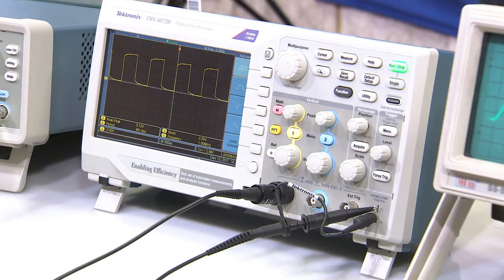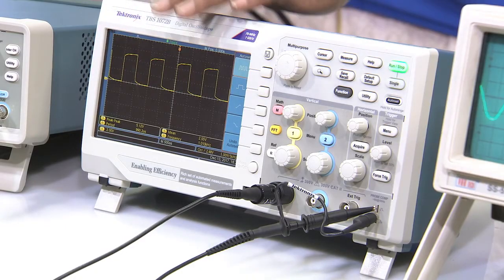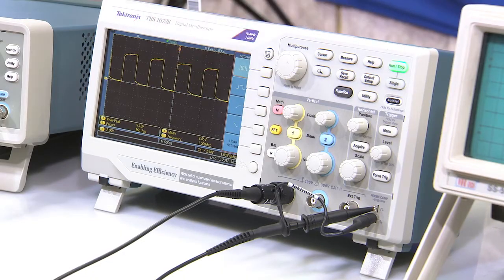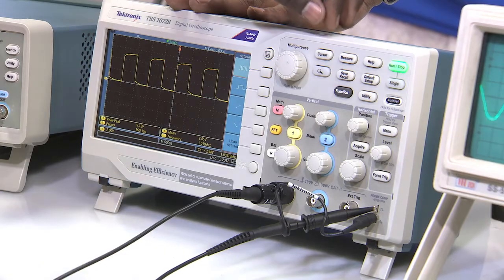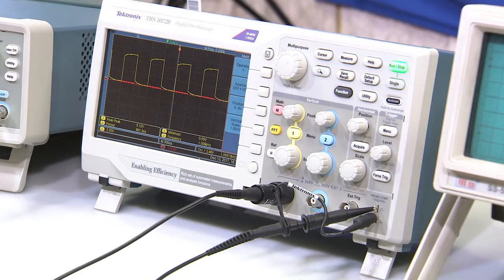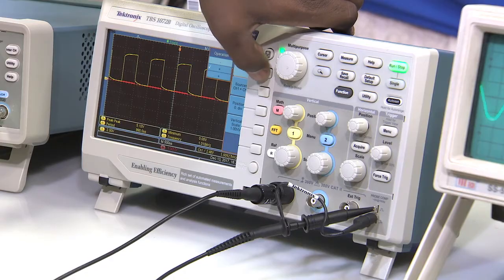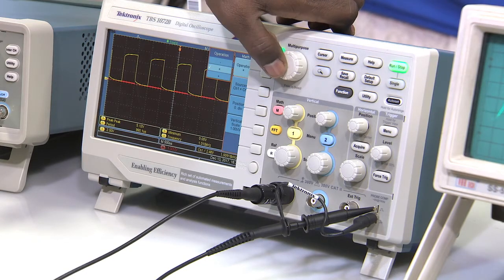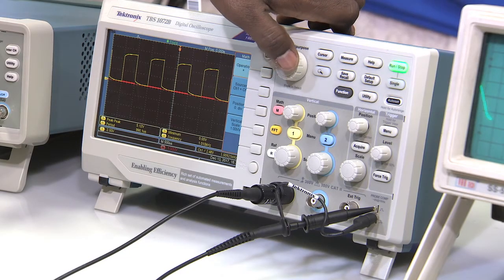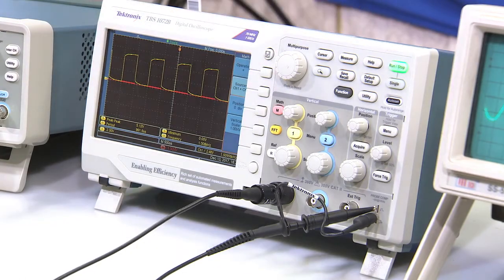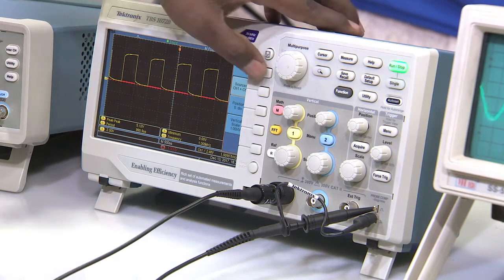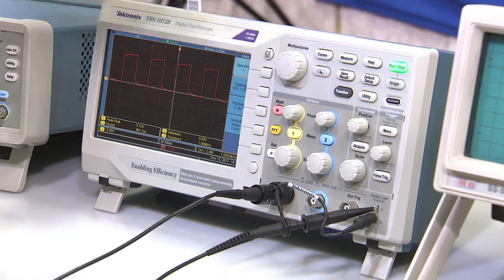Now, let us go to the functions of the oscilloscope. We have seen the vertical and the horizontal. Now, let us see the math function, which is M, the math function, right. So, what is this math function? Is it an operation, is it a multiplication or addition, or a subtraction? Suppose I want to do a multiplication. Then I have to use this operation, and I have to apply two different voltages. Right now only one signal is given. If there are two signals, I can use the two signals to multiply and I can get that function. Similarly, I can do addition, I can do subtraction, all right.